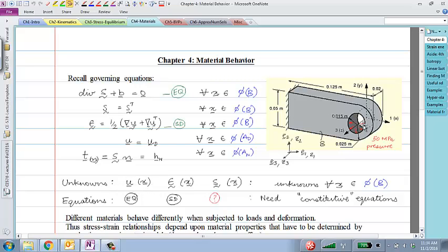So how many scalar fields does this represent? Displacement at any point in the body is clearly a vector field, right? It has three components. So indeed there are three scalar fields behind this. I'm just counting the unknown fields right now. So these are three scalar unknown fields corresponding to displacement. If we assume that the linearized strain or the Lagrangian strain is symmetric, then there are 6 independent scalar fields behind that. That's what we are trying to find.